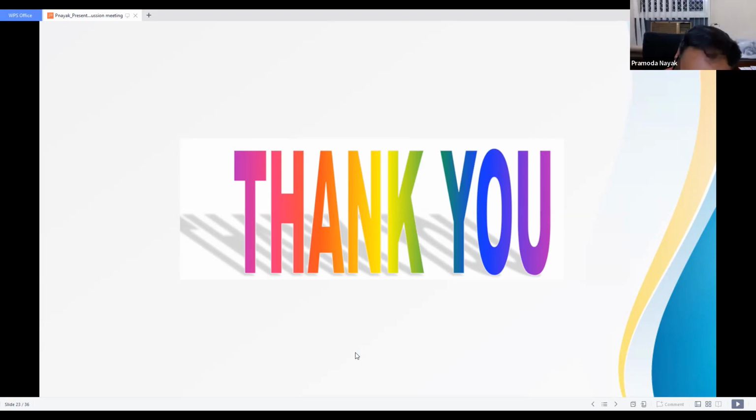So thank you. Yeah, this is a valid question. Mostly reproducibility and other things are the major issue, because when you talk about the CVD, it is not a very straightforward method to prepare this material. The humidity, temperature, pressure, all the conditions are very, very crucial. So one has to be very expert in growing this material. That is one of the challenging aspects of CVD growth.